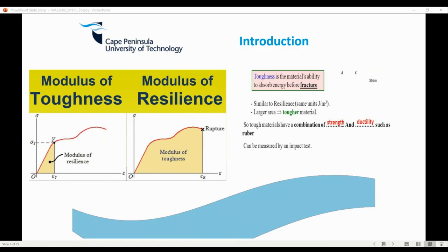I wouldn't say that really. I don't agree with that definition. It's really about that curve, your stress and strain curve, and the bigger that curve is, the tougher it is, and that's really true. I've tested stainless steel impact tests, and obviously at normal temperature this stuff is very tough. As you decrease the temperature to around -20, they become brittle. I've seen it happening. I've done it myself.